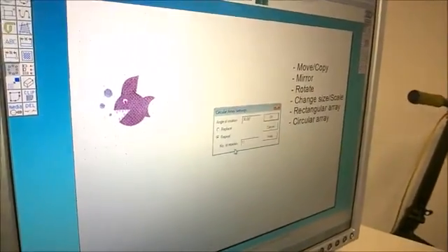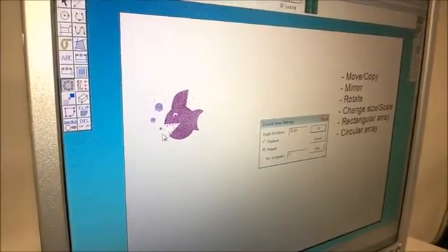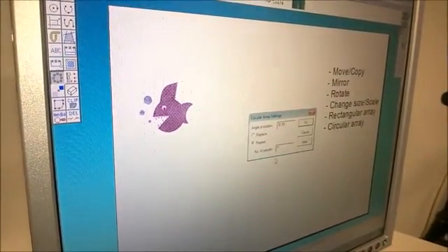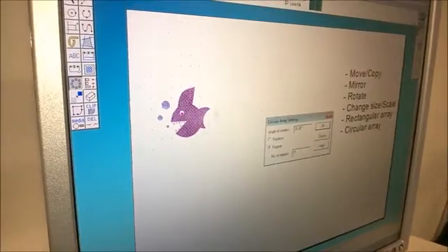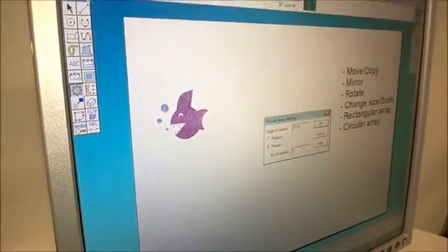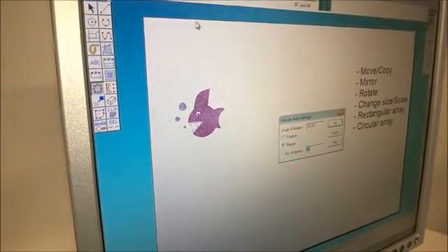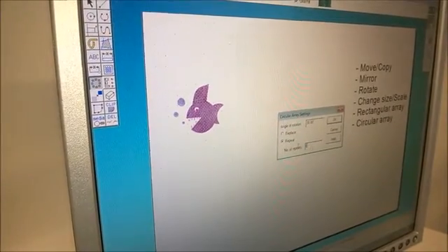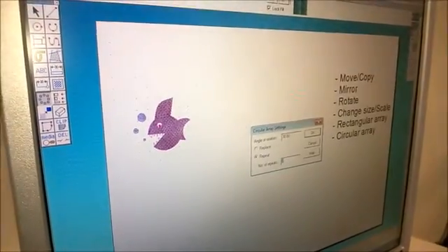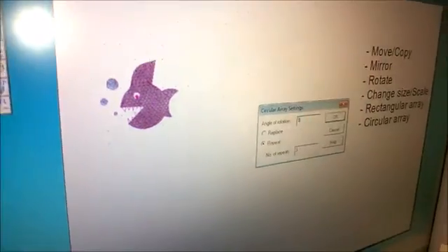Now this is a little bit tricky because again it's asking me to repeat, so I've got to remember that my original shape counts as 1 and any additional repeats count as a second, third and fourth and so on. Now I'm going to produce a very simple pattern that's got 4 shapes that are all set apart, and we think about this a little bit like breaking up a circle. So a circle is 360 degrees. If I want 3 repeats and my 1 original, I divide my 360 by 4 because that's how many I've got in total, and that gives me an angle of rotation of 90.